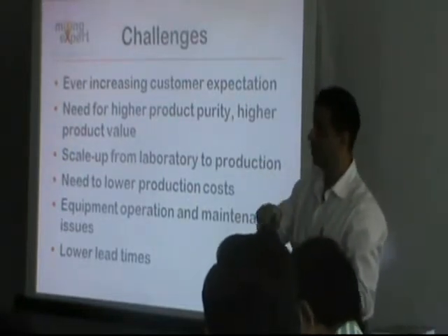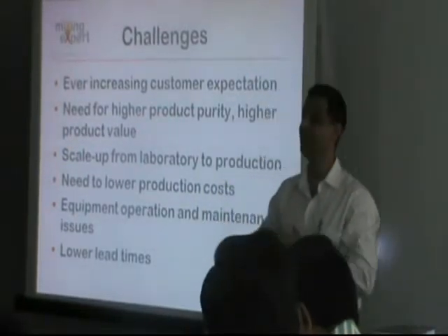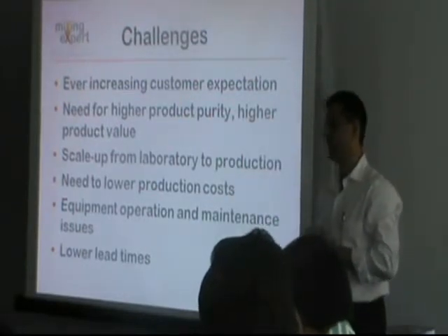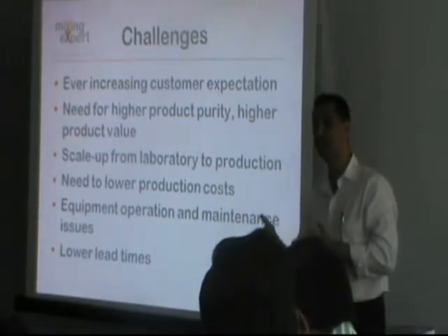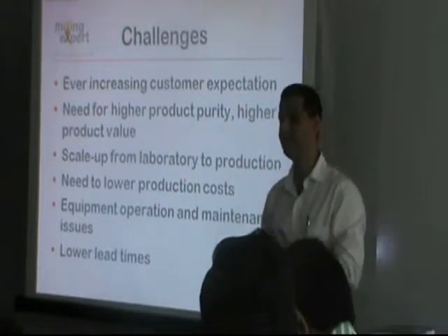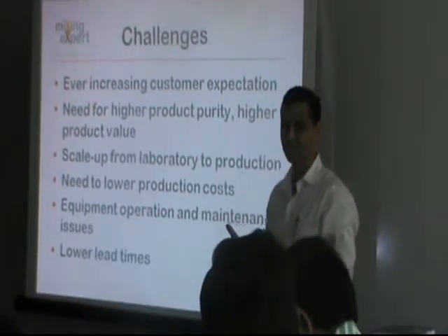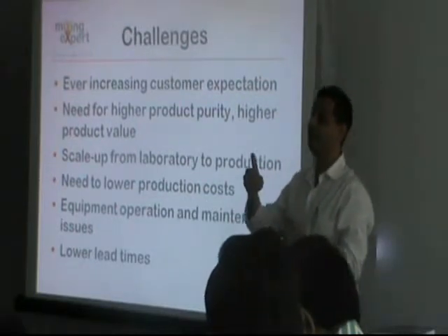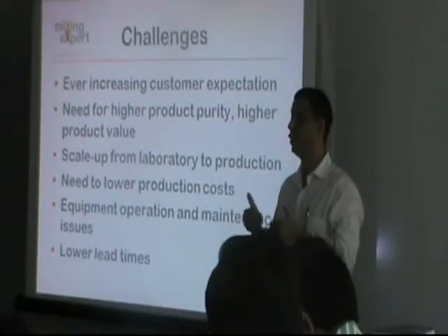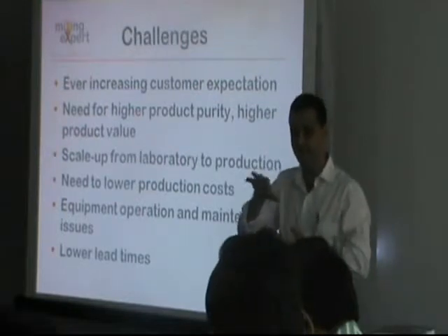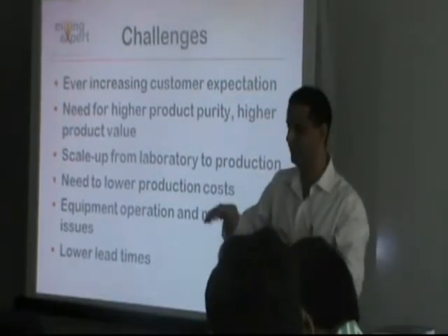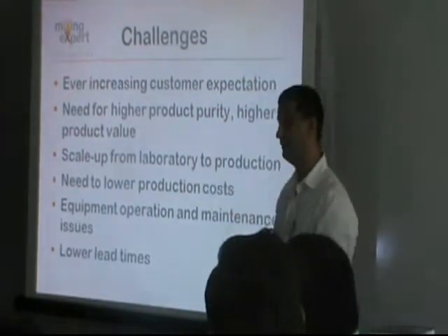The other important thing you have to note is a lot of times you will see that the current doesn't change. These are practical observations. The reason for that is that when the motor is being operated under a no load condition, the power factor is low. Anybody from the electrical background will know, power is root 3 V I cos phi.